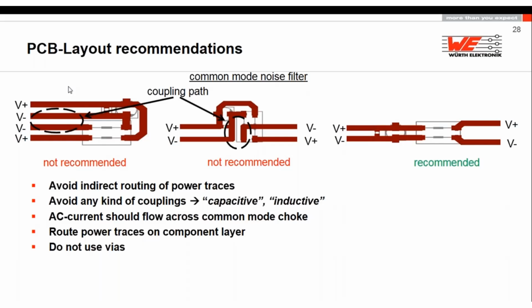If I would not see it with my own eyes, that this is so important, I would not believe it. So I told them, please, can you go to this common mode choke, one side in and one side out? Redesign number two. One side in, one side out. With this one, I saw already the PCB, the Gerber file. He sent me the Gerber file. I said, no, please pay attention.